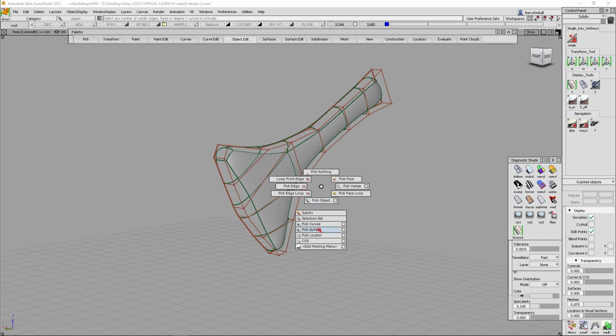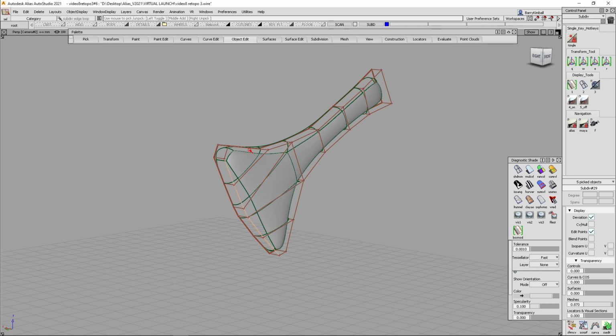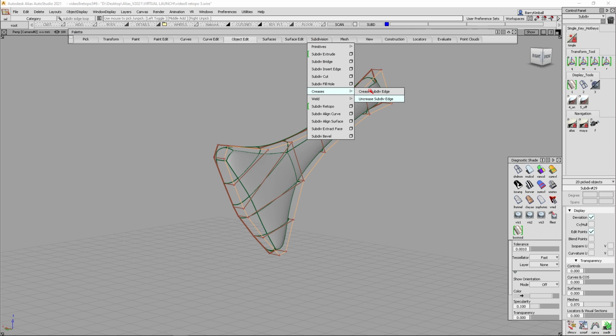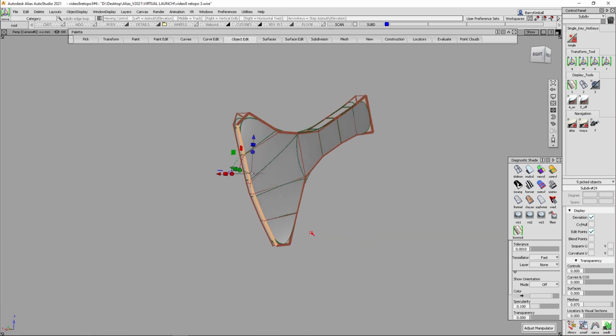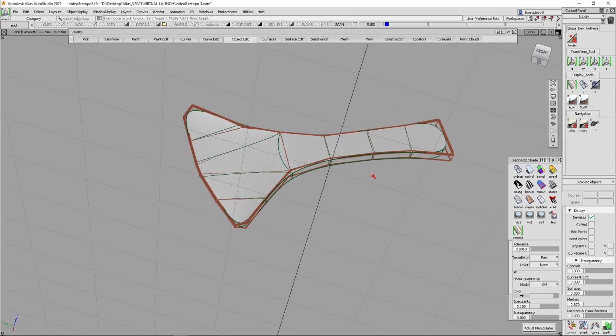That's pretty good. And then I am going to pick an edge loop here, shift edge loop here, keep going. The edge loops are not going to chain past where it finds a 4 directions. Okay, so it only can chain if it knows where to go. If it gets multiple choices, it stops chaining. And then I'm going to do a subdivision crease, crease subdiv, and maybe grab this edge loop and move it over a little bit. Oops, Control Z, move it over a little bit.